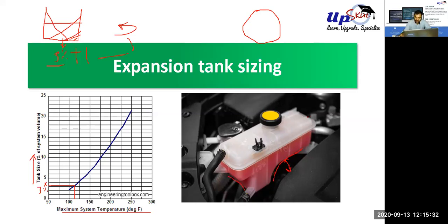Inside the expansion tank, you can see these lines. These are compartments. The purpose of this is to prevent the thing that I just said. If I have compartments like this, now when the vehicle goes through a turn, only the coolant in its own compartment will tilt like this. Now the entire tank is not getting empty. So that's the advantage of compartments.